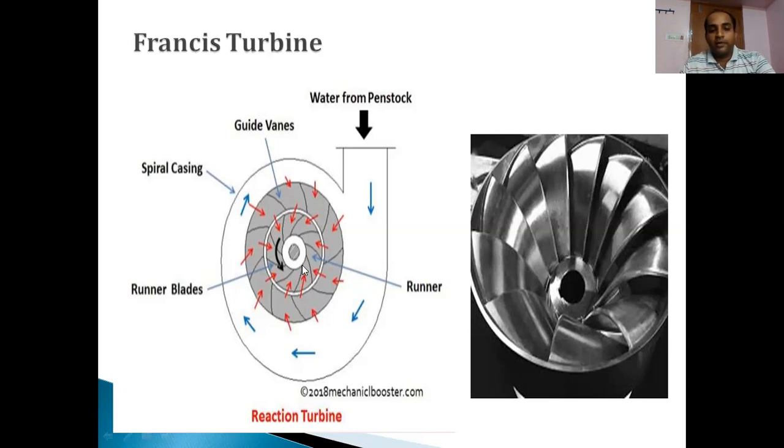In the previous Pelton wheel turbine, I was telling you that to increase the kinetic energy, we take the help of a device known as a nozzle. But here we don't have a nozzle. Instead of that, if you observe the runner blades carefully, see here, this entire view, the cross section area starting from this end, as I move on to the other end, what happens? It goes on increasing, which means the blade designs and the mountings of the blades have been made in such a fashion that these blades themselves act as a nozzle.